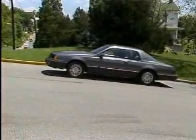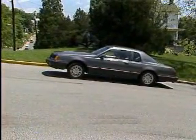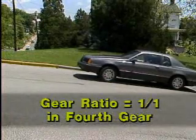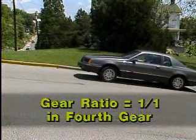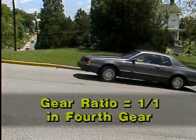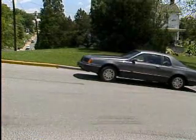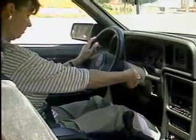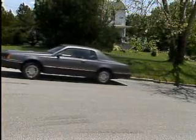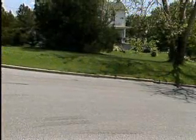Well, if you try to start up in fourth gear, you may spend the rest of the day at that stop sign. That's because the gear ratio in fourth gear is about 1 to 1. Your potential for reaching a high speed will be there, but there's not enough torque to get you going. Another gear arrangement would be more suitable in this situation. In first gear, you have enough torque to get you going again.